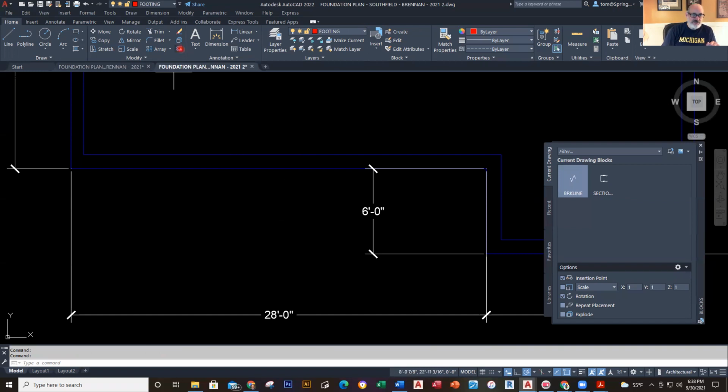So I'll go to offset, and I start my offset command. My offset distance is 4, type in 4. Now, I got to go to my settings. Okay, now notice that there's settings right here. I've got layer. Well, what's layer doing there? I'll click on layer, and what I can do is I can say current or source. Source is the default, but if I click on current, watch what happens here. I go to current, and I'm going to use 4 inches. I'm going to click on this, and I can go this way. Isn't that pretty? Like that.